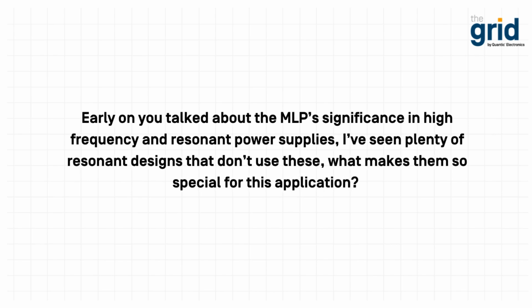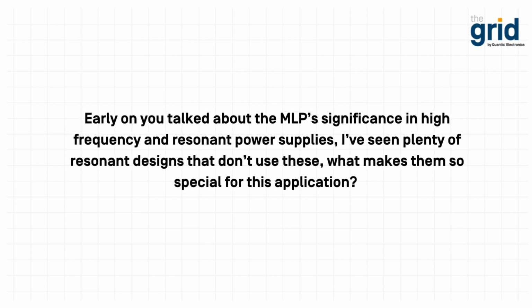I think we talked a lot about what makes them special in general, but yes, other technologies exist out there, like your traditional wound films, right? A lot of the bidirectional, inverter applications today are using wound film capacitors. A lot of the resonant power supply topologies are using wound films still.